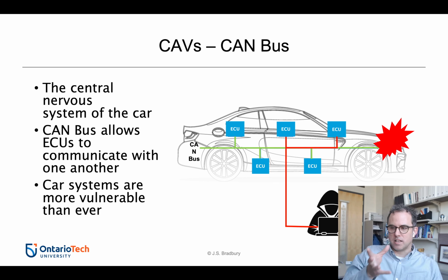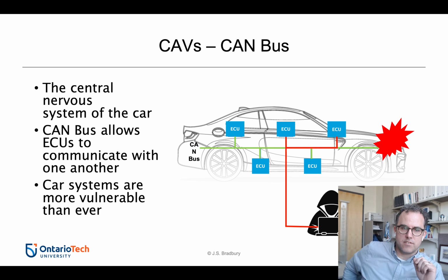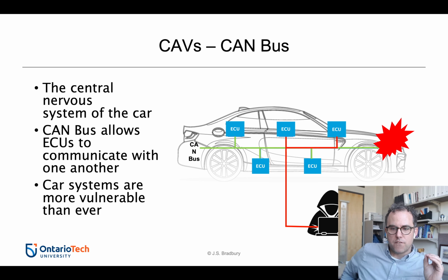And the types of attacks can be a whole bunch of things. So you might think of a picture where somebody is actually trying to connect in, right? Well, some attacks actually require physical access to the vehicle. There's something called an OBD port underneath in the footwell of the car under the driver's side, where you can connect in a device and connect your computer to the car. That's often where insurance companies put monitoring software in exchange for lower insurance rates. But it's also the port where, when you bring your car into a garage to get diagnostic information, they hook up the diagnostic computer. So if an attacker has physical access to the vehicle, they could try to connect through that.